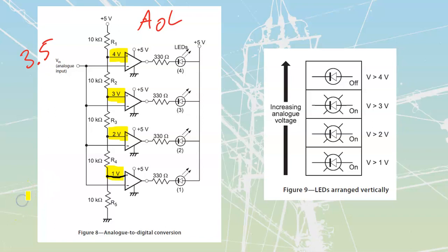Same deal. We're just going to compare these. Now we are going to have 3.5 compared to my 2 volts. That's going to be my reference over there. And I see that I'm going to be plus 1.5, so I'm going to be a positive value. That positive inverts and becomes a negative. This one is also going to go and ground down. So now we've got 2 of these that are going to be grounded down. Each of these means that my light is going to go on.